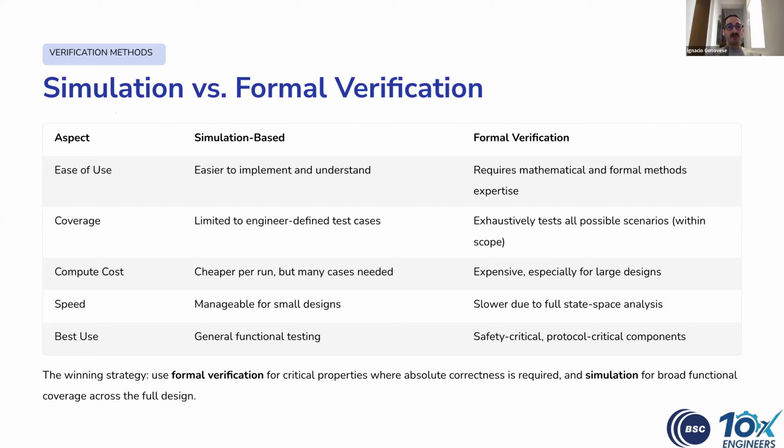And for the best use, simulation is general for functional testing, and formal is better for safety critical or protocol critical components. So we need to use formal for critical properties requiring absolute correctness, and simulation for broad functional coverage.